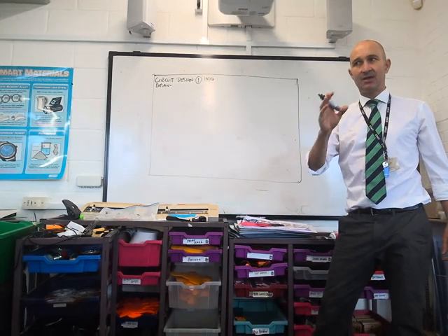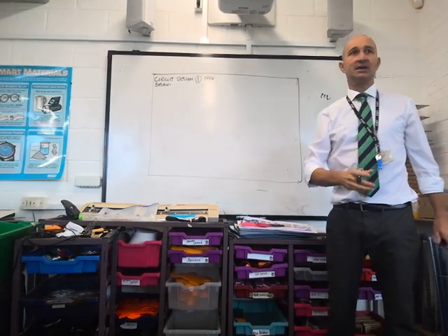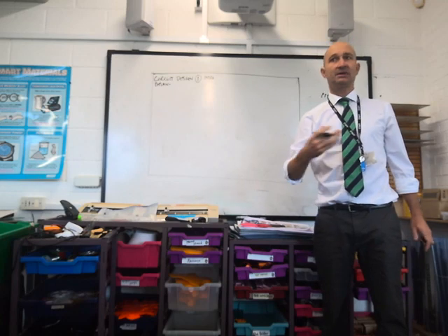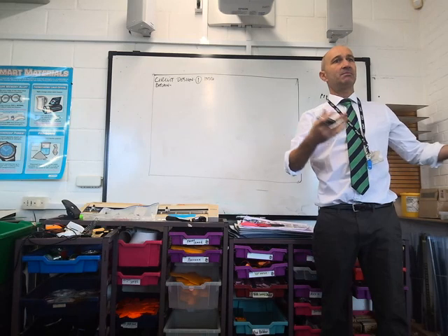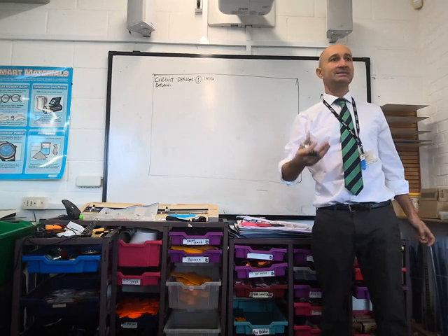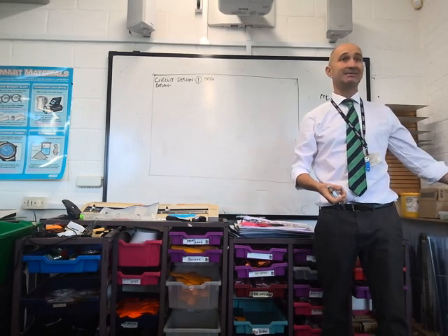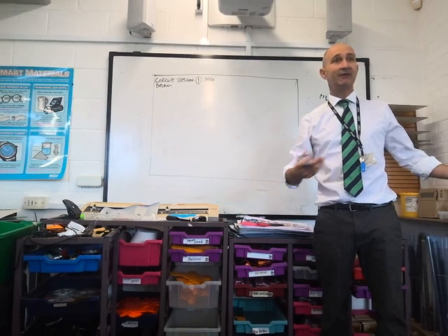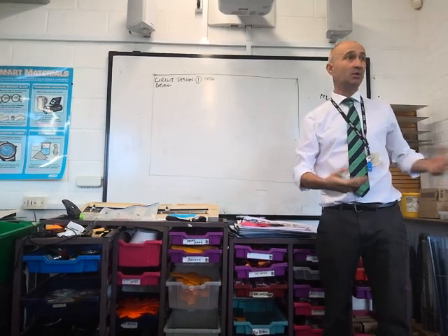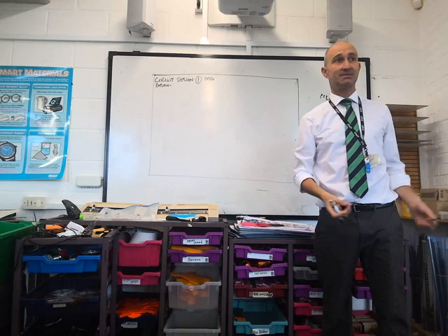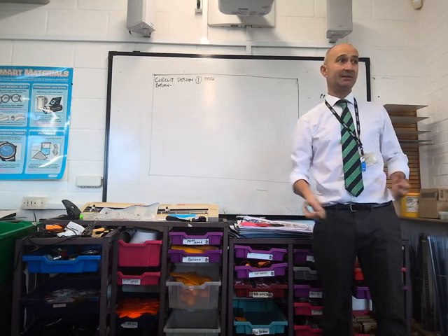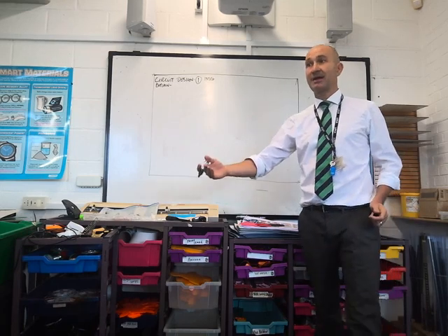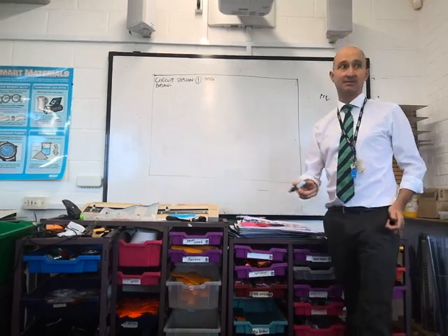On the last circuit, it wasn't very successful because it took a long time for the program to load. The LEDs came on, but they weren't bright enough. The buzzer sounded, but no one could really hear it. Therefore, I'm going to introduce different components like a transistor. And that will hopefully increase the sound. And also, if I use a different program, hopefully the program will be faster.